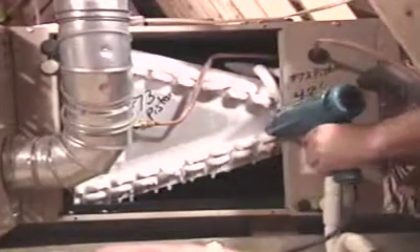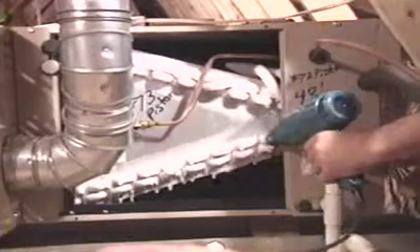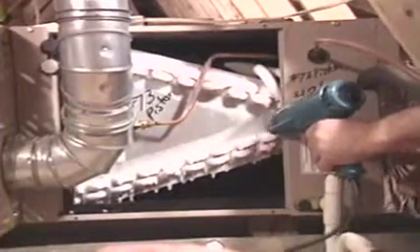Start by turning the unit off. Then attach a lock and tag. If it's not accessible, the evaporator coil can be defrosted simply by allowing the blower to circulate air over it. In this case, the evaporator coil is accessible. It can be defrosted either by spraying hot water over it or by using a heat gun. Here, a heat gun is more convenient.